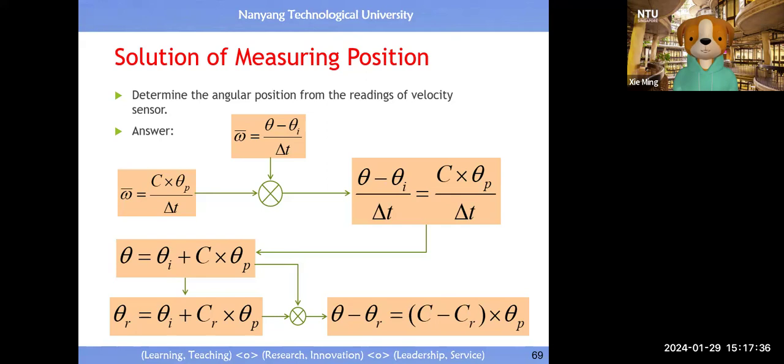This equation helps you understand why we need to do so. For each joint, the robot needs to find out what theta R is. So the robot, once powered, just does some random movement. Now you understand why all industrial robots need you to do the homing first before you can use it.